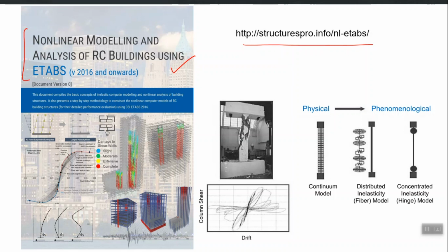On the other hand, a nonlinear model requires a complete nonlinear stress strain curve of a material in order to completely define it, because the nonlinear model should have the capability to know what will happen to our material at different load levels, when that material will crack, when that material will yield. That can only be defined using a complete nonlinear stress strain curve. So this is an example using which you can understand how much input is required to actually construct a nonlinear model. Similarly, take the example of a simple beam.